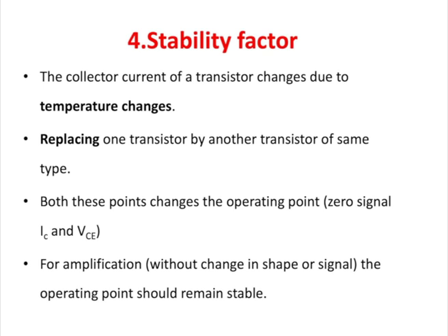Even if the temperature changes, I don't want the collector current to change. What is the second point? Suppose I am replacing one transistor with another transistor. Even when replacing one with the other, I don't want changes in the collector current. So I want to keep the collector current fixed. Whatever parameters I change, that combination is called a stability factor.